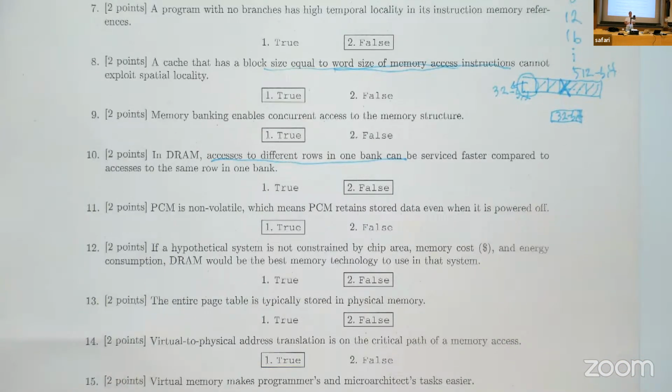That means you have a row enabled. Basically, this access pattern will have a lot of row conflicts or bank conflicts. This means that you enable a row, you spend some time to satisfy the timing parameters, and then you precharge that row, you enable another row, you precharge it, enable another. It's like a double-sided RowHammer attack, if you remember that.